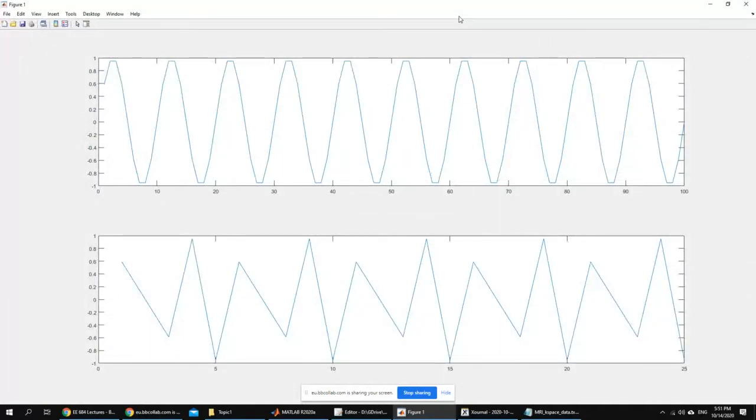When you have aliasing, what happens is you're sampling a perfect signal, and because you have undersampling, you do not have enough samples, you end up with something that doesn't represent the original signal. And this will go to the other side and represent something that would have the spectrum of the original signal superimposed on its aliases, on its periodic extensions.